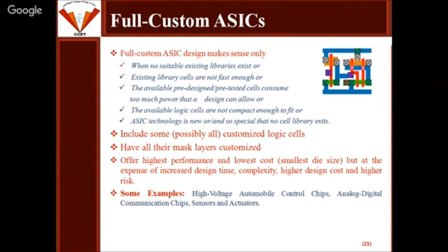It means when the foundry made that device, suppose a 22 nanometer MOSFET is designed, then what are the values of the parasitic source to drain capacitance or drain to gate capacitance? What are those parasitic capacitance values? What are those parasitic resistance values? That is defined in the model file. You can open the model file and find the different parameter values given. And then simulation is performed on the basis of that model file.